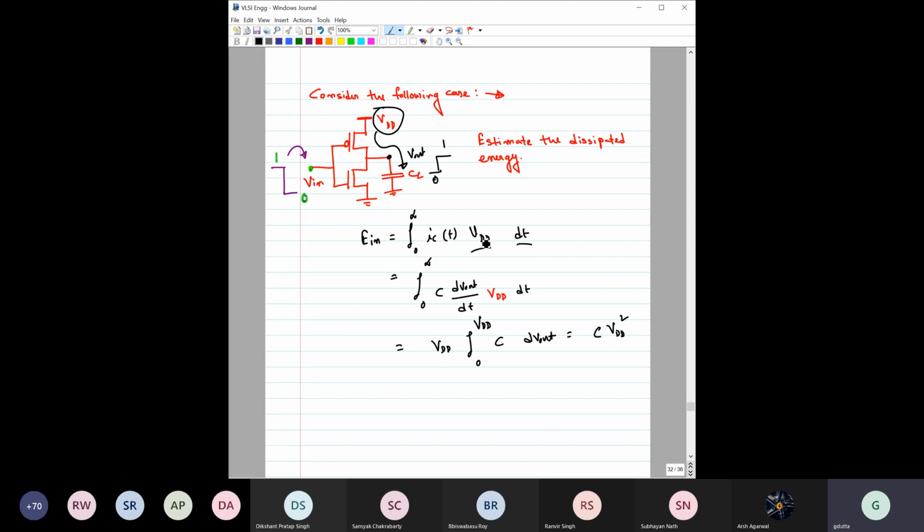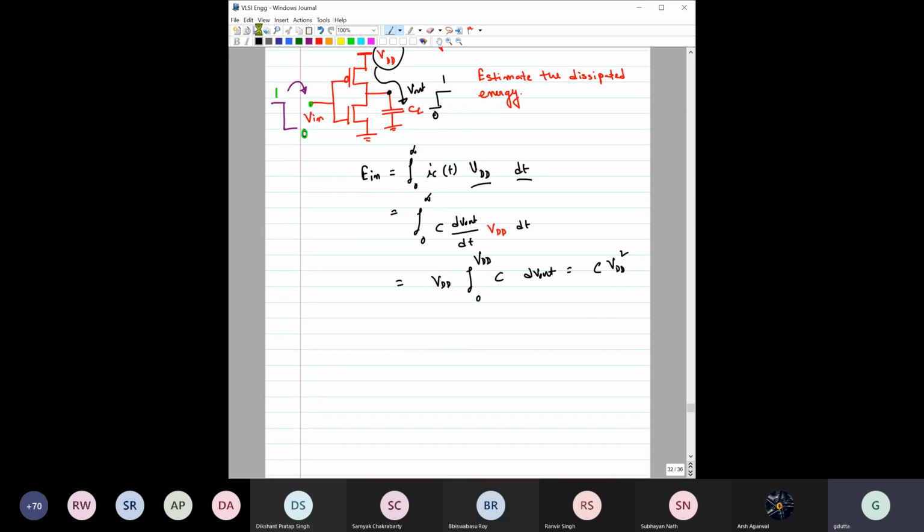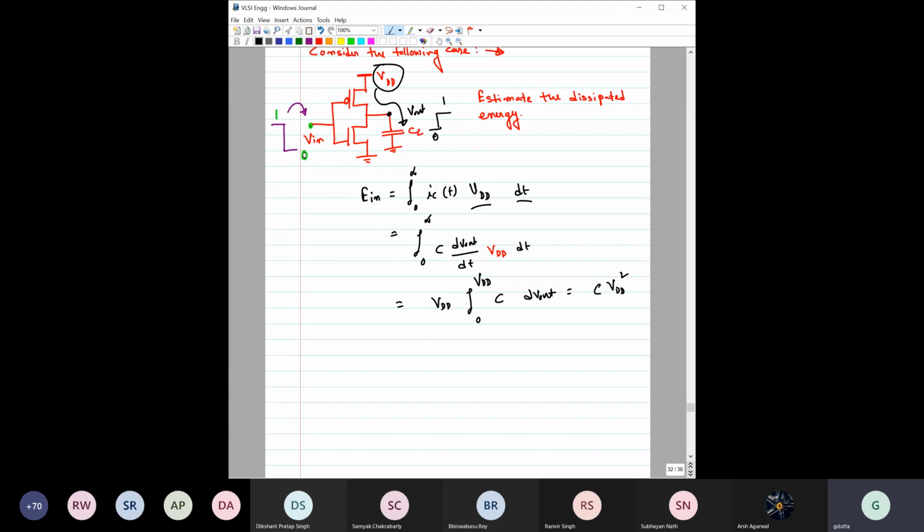So there, the VDD is constant. So, sir, the extra energy is lost in the PMOS while the current flows. Exactly. That is what I wanted to show you from here. So you have understood, right? This is the energy that has been taken from this VDD during this charging process.